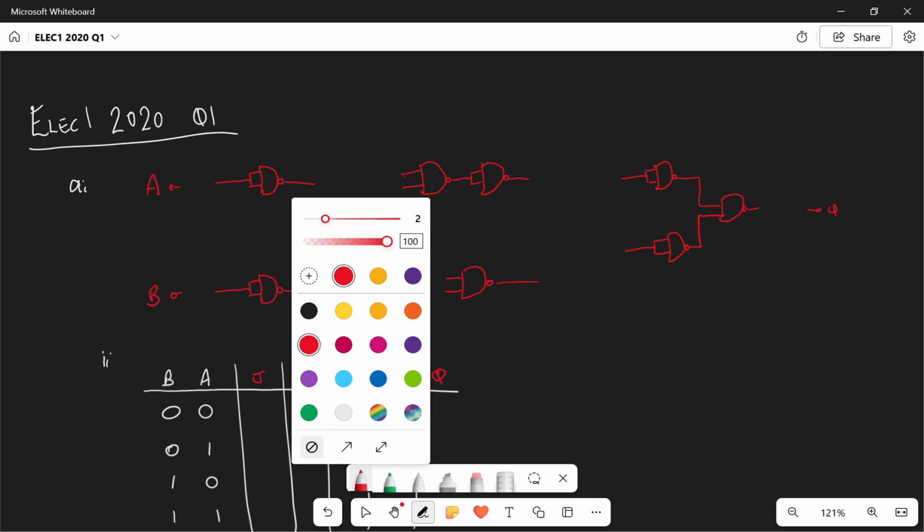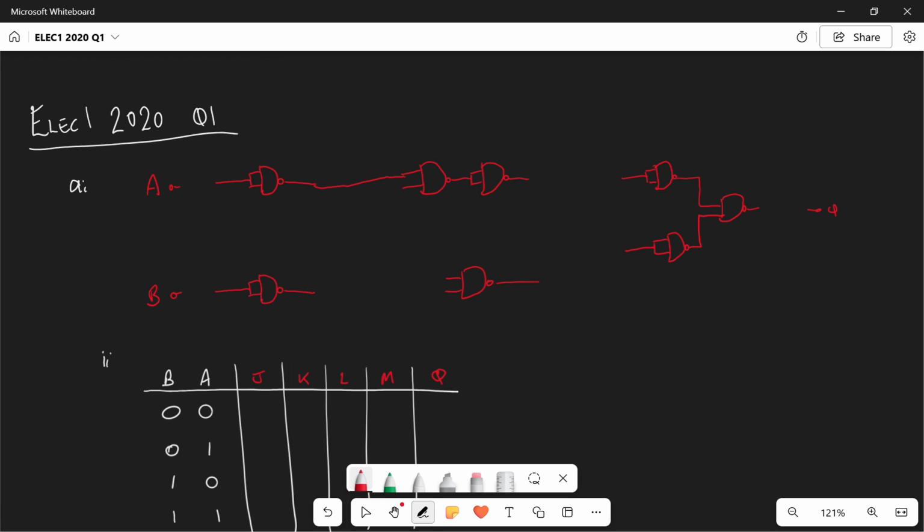So let's just do that. So the first of our attachments is across the top there. And then we can do the attachment across the bottom if we wanted to. The attachment from the output of the NAND gate and AND gate. And then we've got those cross attachments where A goes down to the NAND gate at the bottom and B goes up to attach to the AND gate. And then we just got to attach the output and the inputs to make sure that we've got our complete circuit diagram.